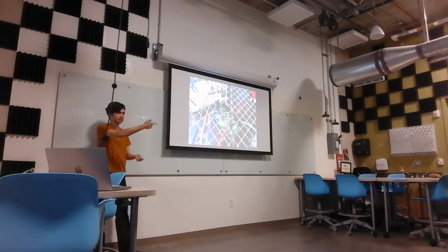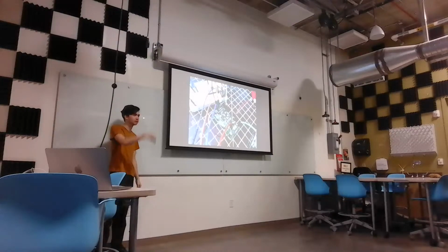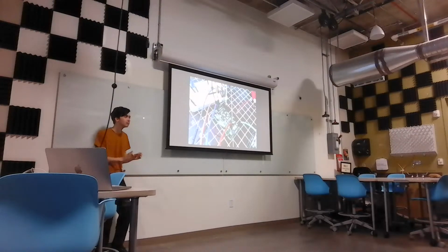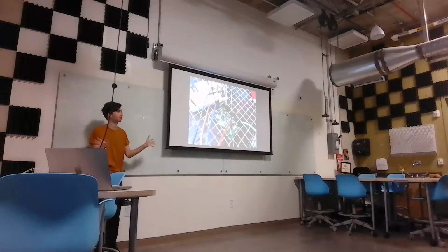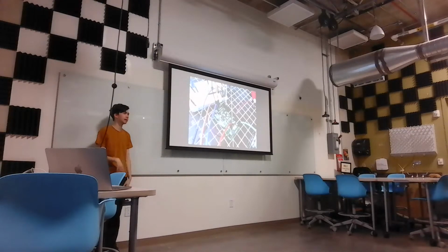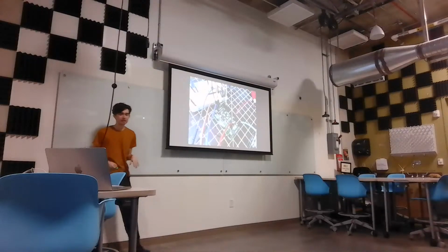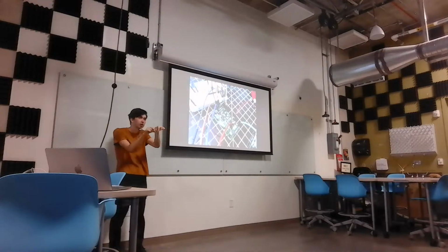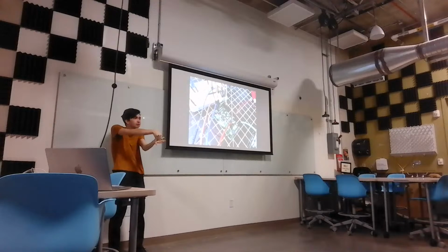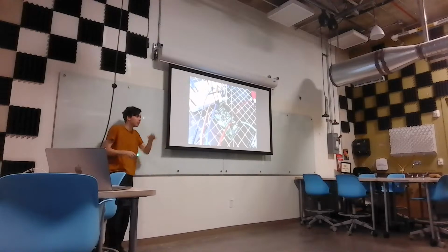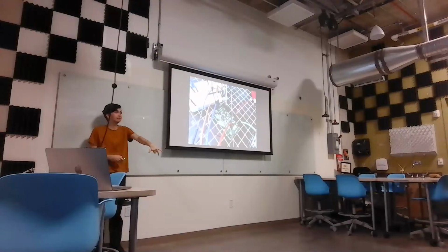So when I was plugging these dinky little capacitors that Vision had into it, they weren't doing anything simply because they had legs. Those legs instantly just removed the benefit of the capacitor. Those legs being like half a centimeter long was too long. That's a high frequency. We're dealing with 300 kilohertz here. So eventually I realized that I could actually just solder another SMD capacitor. Thankfully, the layout made it possible for me to do that. And so I did it.